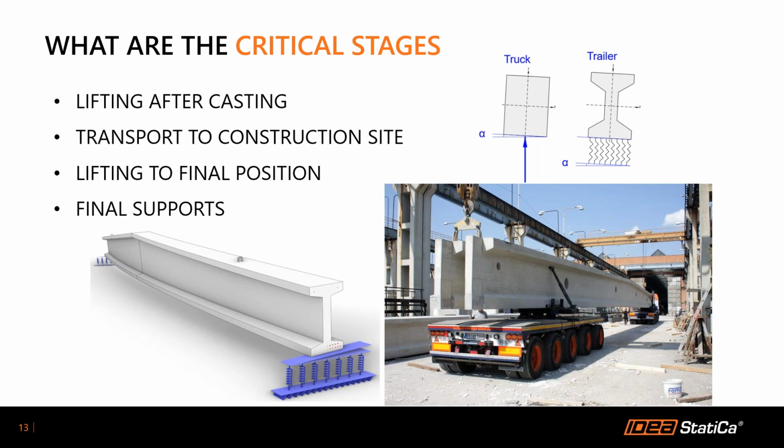Then the next critical stage is the lifting to the final position, which happens on the construction site when a beam is being moved to its final place. And the next stage is the final supports, because even if a beam is moved to its final position, we may not have any lateral bracing in place yet. So the beam can still be prone to lateral torsional buckling.